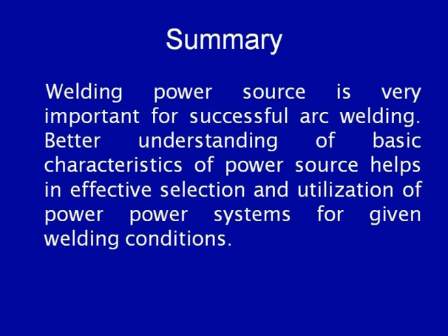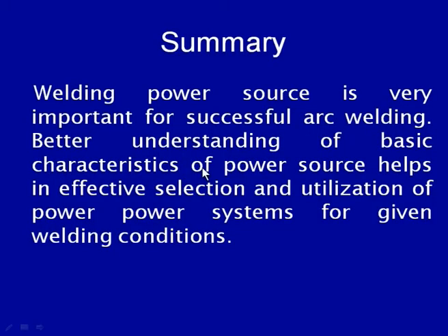Now, we will summarize this lecture. We know that welding power sources are very important for successful welding, because it is necessary that heat is uniformly generated, so that constant and uniform heat can be obtained with the help of the proper kind of welding power source. For that we can select constant current type, constant voltage type or rising characteristic type of power source. And how can we maintain the arc length? For that purpose we can use self regulating arc or the feed drive system with variable feed motors.